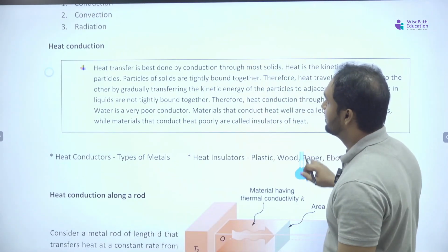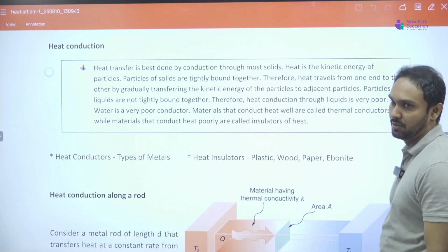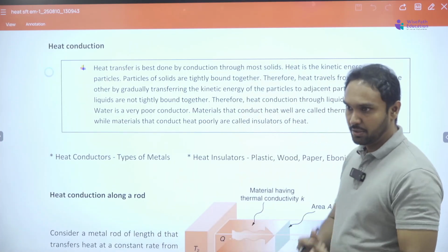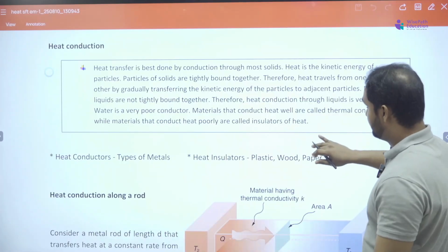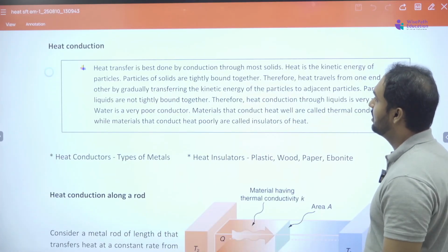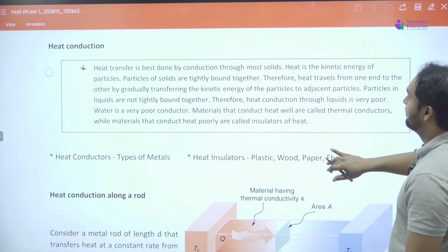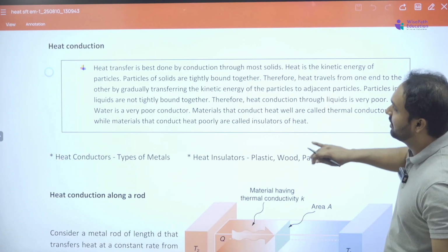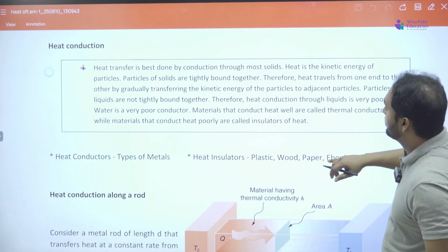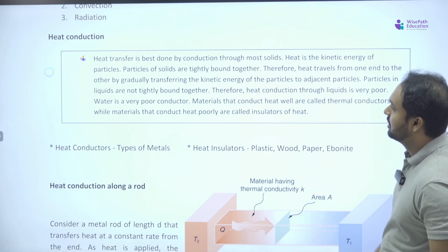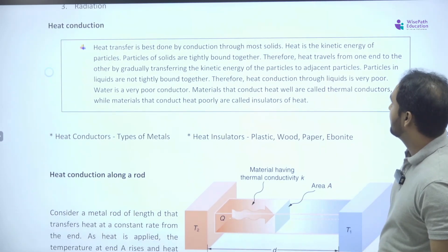Heat transfer is best done by conduction through most solids, because only in solids are the particles attached together, right? So heat is the kinetic energy of particles. Particles of a solid are tightly bound together. Therefore, heat travels from one end to the other by gradually transferring the kinetic energy of the particles to adjacent particles. Particles in liquids are not tightly bound together. Therefore, heat conduction through liquid is very poor. Water is a very poor conductor.